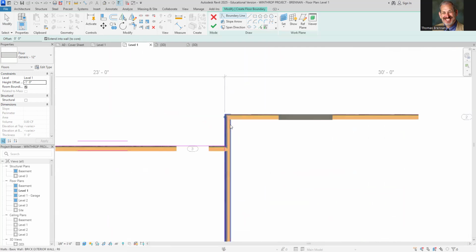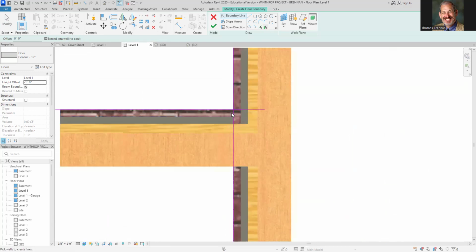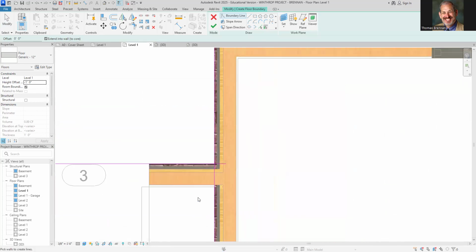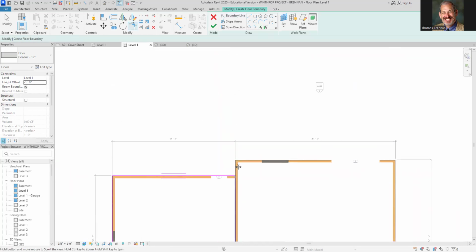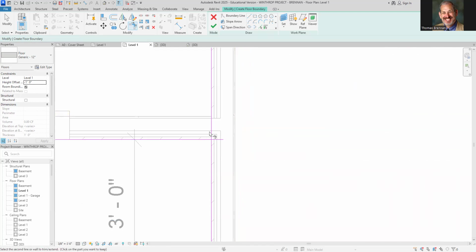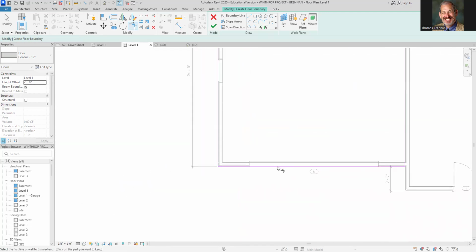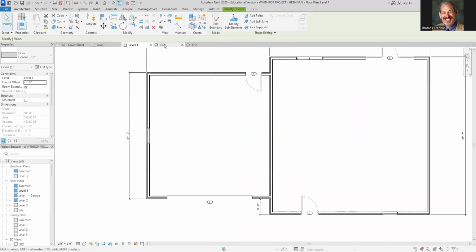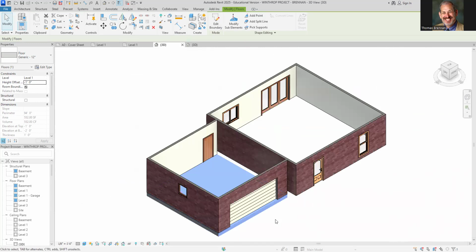Now at that point, I have to verify that those are connected. You guys see that right there where those are overshooting each other? Yeah. All right, and we've learned before that's a no-go. So I'm going to go here and use trim extended corner, click on this line, click on this line, and that cleans up that corner. Same down here. And if it's easier to put this on hidden line, it might be. That way, just go to here and here. And the rest of it should be pretty good. Now, once I've got that, hit the green check mark. We're there. I go to 3D, and now there it is right there.